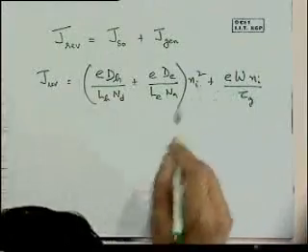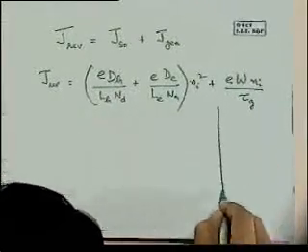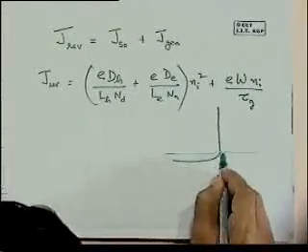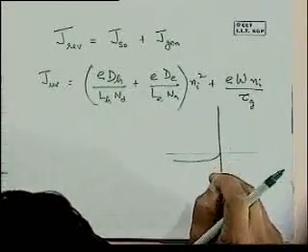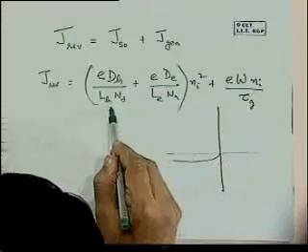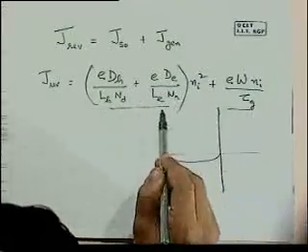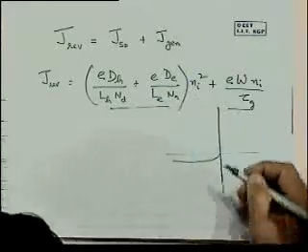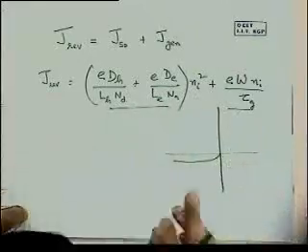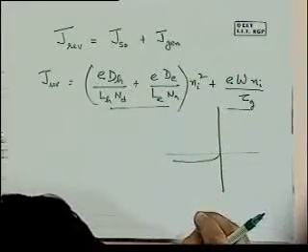What you're saying is correct. When we look at the plot, the current is going to be on the negative side. The flow is in the opposite direction to when we have forward direction. You're right. But when both these currents add up, both of them are in the same direction. So that's why I've written both as plus. But the actual sign of it is flowing in the opposite direction to the case of forward biasing. You're correct.